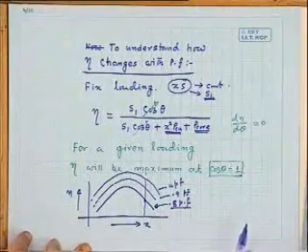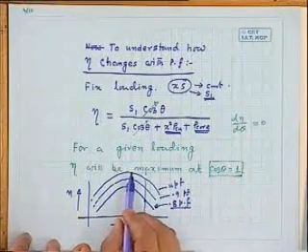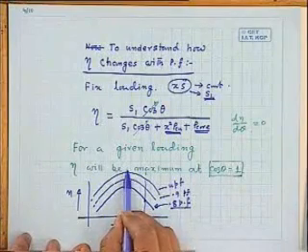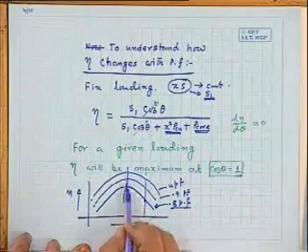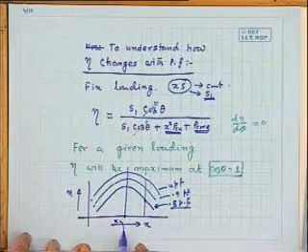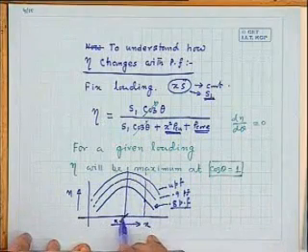Now the question is, therefore, from the use point of view, knowing that the efficiency versus degree of loading curve for a given power factor will be this way, we can at least say this much: the maximum efficiency will be obtained when we see that the power factor of the load is unity. These are all the points corresponding to maximum efficiency, where x equals root over P core by P copper.